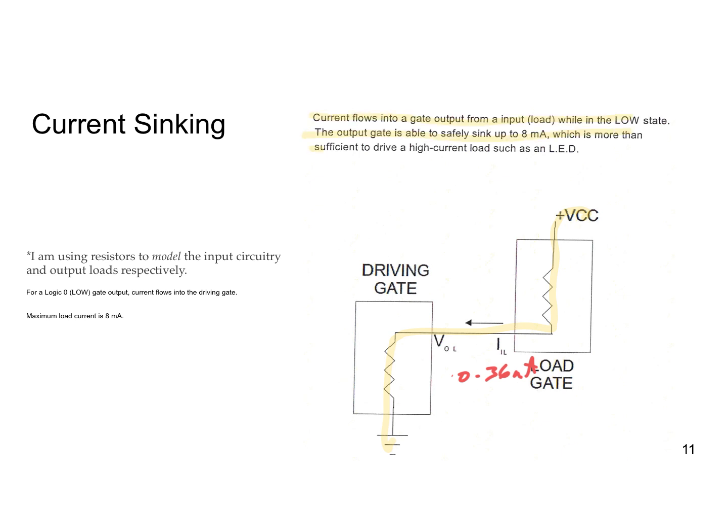Okay, that's why you can't directly drive an LED with the gate. What I mean by that is, okay, so this is not going to work because the LED is going to draw more current than is required.